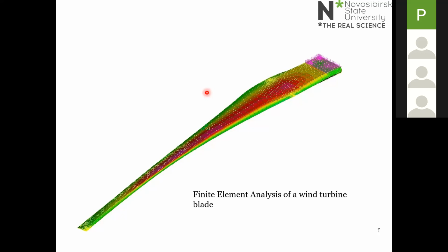And this is quite a complex process, because even on a small wind turbine blade like this, there could be a large number of layers of reinforcement. And most of those reinforcing layers are in the radial direction, but there is also reinforcement at plus or minus 45 degrees. And the reason for that is that we don't want a wind turbine blade to twist.